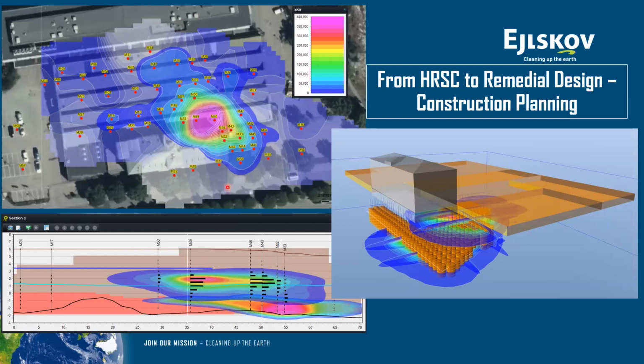any sign of contamination. We were able to separate the soil contaminant mass from the groundwater plume. We were able to generate a very detailed profile of the bedrock, which made perfect sense with the groundwater flux. The light blue zones are where the bedrock is at the deepest. And in this case, we could see a plume migrating off-site, originating from the source.